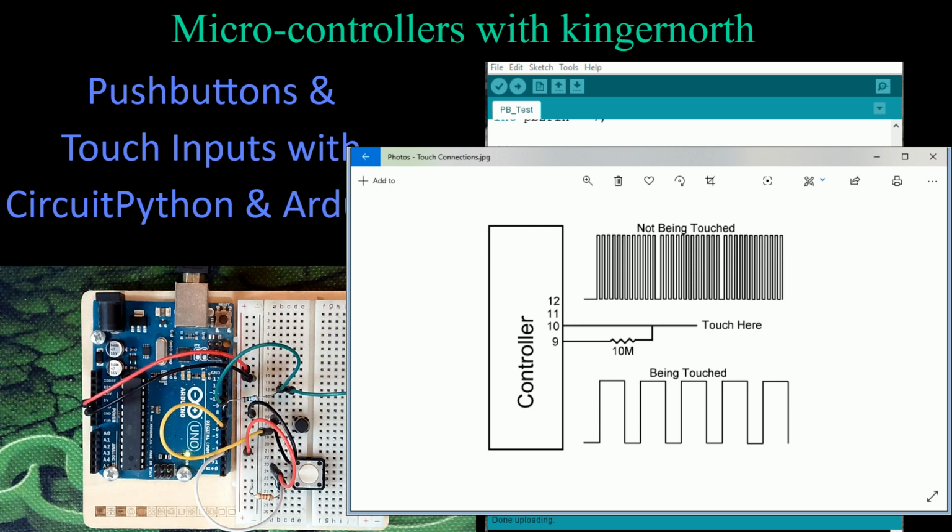If anybody's got a car where you reach over the handle, but you don't actually touch the handle, and the door's unlocked if you have the key fob in your pocket, that handle has a capacitive touch circuit on it. What it's doing is reading as if you're close. Now, I chose the value of 10 million. You have to choose a value of at least 1 million for this even to have a chance of working.